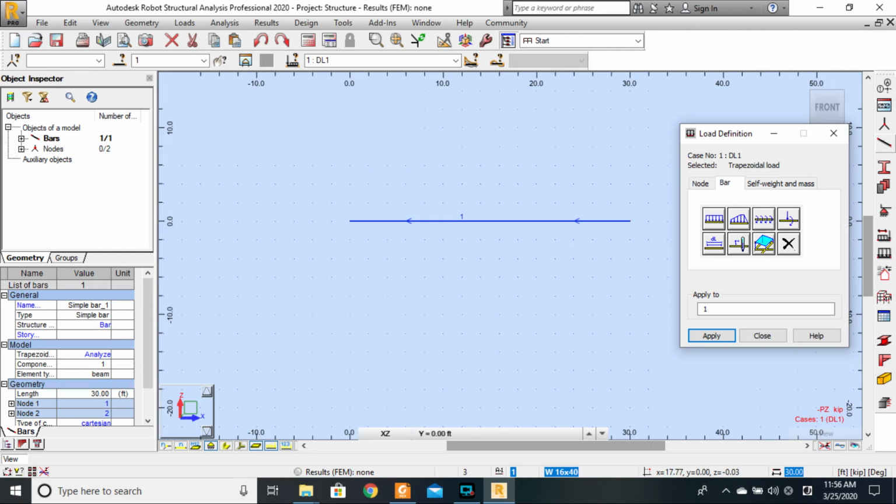So when I move here and cross the middle, it is now the opposite direction. If I click in this position, Robo understands that this is the first node and the second node is the other way. But we want P1 to be applied where? On the first node this way, and then to the other way. So this is the way we have to click.